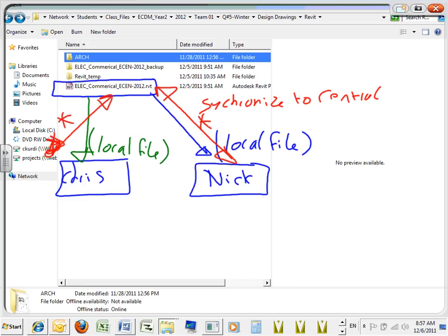At all times, you will have a file on your laptop of everything that you have done. But I don't want you to get into the habit of opening the local file. Always open the central file. It will say, do you want to override the local file that you have in your machine? Say yes, and start working. Cool? Are we cool with the interaction?